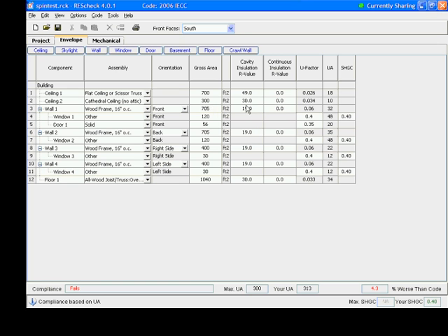It's 300 square feet, and that allowance that's in the code, that first 500 can be that minimum of R30, the lesser insulation requirement. REScheck does not penalize you to do this for 500 square feet of it. So that value is fine. That's the minimum. You're not getting any trade-offs. So right now we're meeting minimums on our insulation.